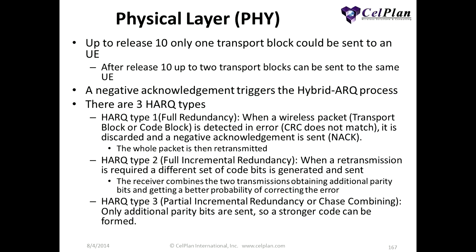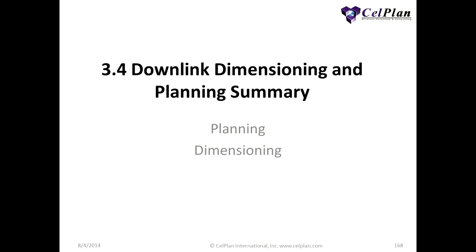So the UE doesn't receive how many bits were sent. What it does receive is the TBS index and the mapping. By the mapping, it calculates the number of resource blocks, and by the TBS index, it calculates how many bits were sent. So it's an indirect calculation again.